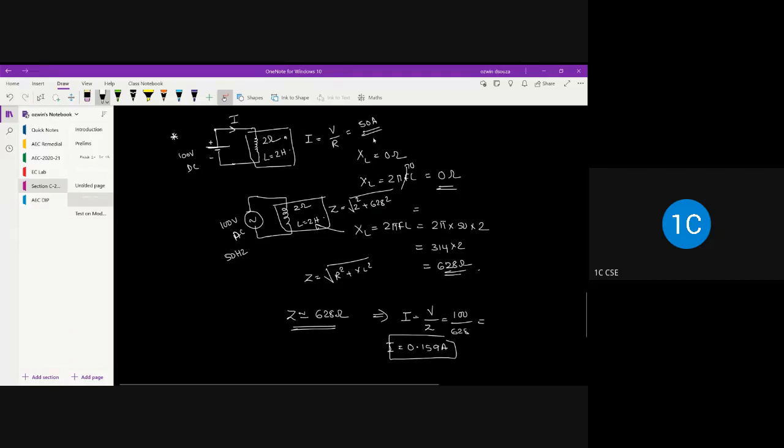Due to excess heating, the coil may get damaged, because the coil resistance is very small and cannot limit the high current. That's the reason we never connect pure DC to a transformer. If you connect it, there will be a high flow of current, and the coil may get short circuited and damaged.